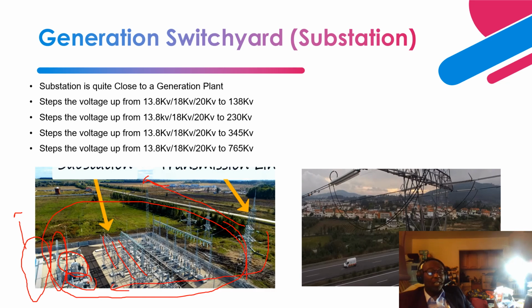So at the same time that you are pushing, you are generating power out there on the transmission line, you should have a redundant scheme, a transmission line network that will go through a step-down transformer that will basically step it down to a medium voltage level, let's say 4.16 kV or 6.9 kV, right? They call it auxiliary power, right?